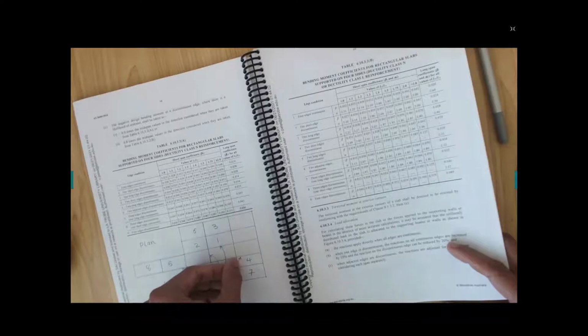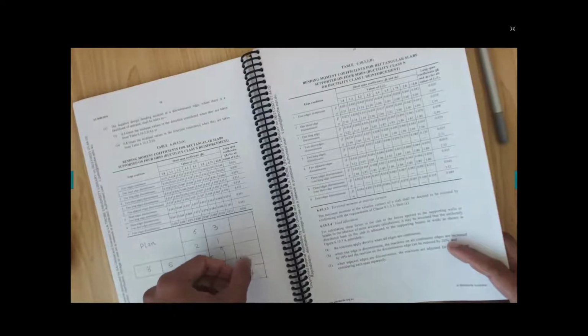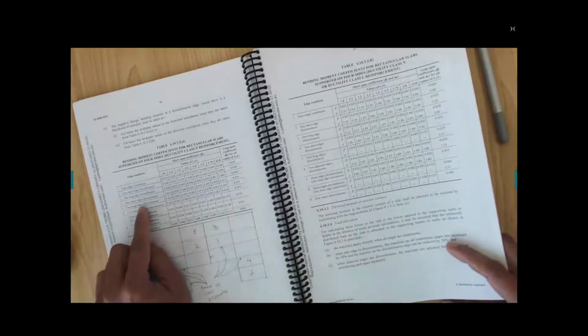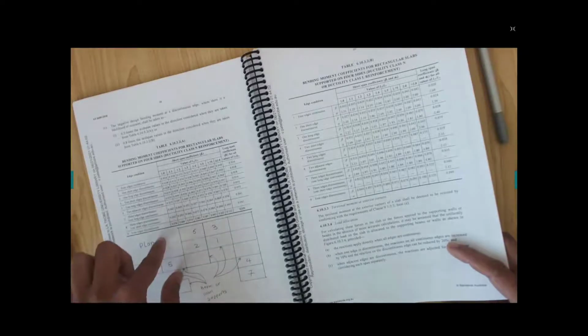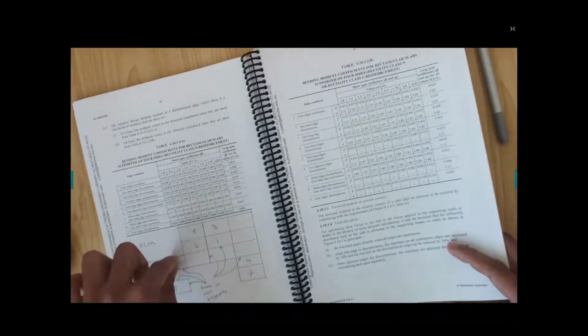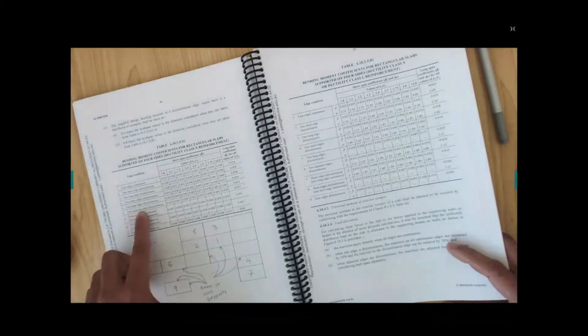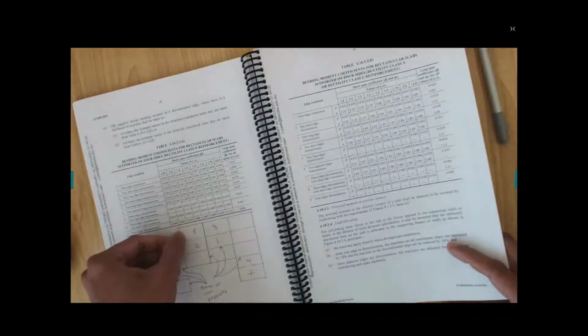You remember this kind of balcony. If you have buildings, you have a balcony, and your balcony is discontinuous in the short edge, and again continuous here. You have some kind of support. So you have this case number 4. 2 long edges discontinuous, number 5. So you can see again a balcony, but it is narrow and along this length it is wide. So you have these 2 edges continuous and the 2 short edges are discontinuous, or 2 long edges are discontinuous. Number 6, 2 adjacent edges discontinuous. Adjacent edges meaning they are meeting each other and they are discontinuous.